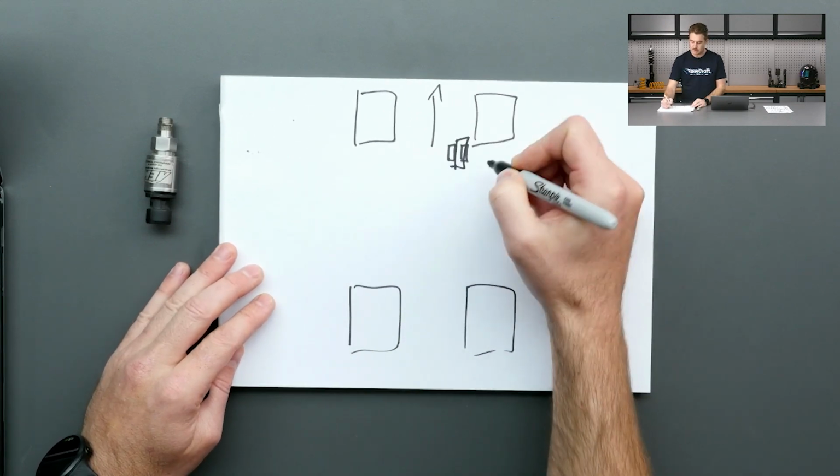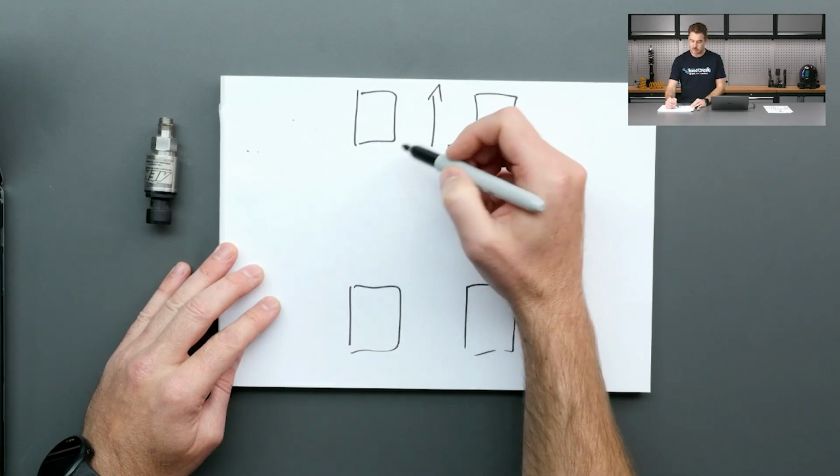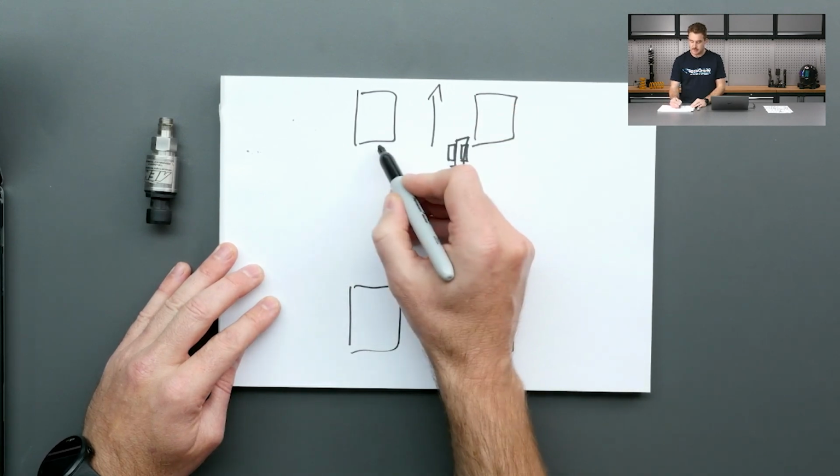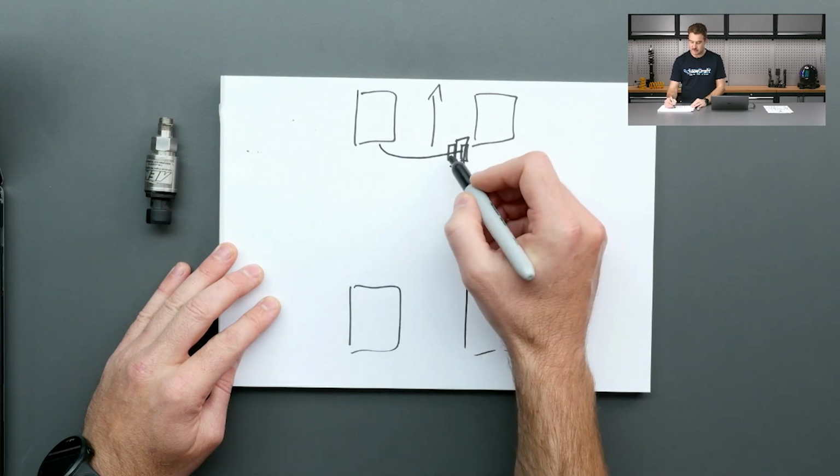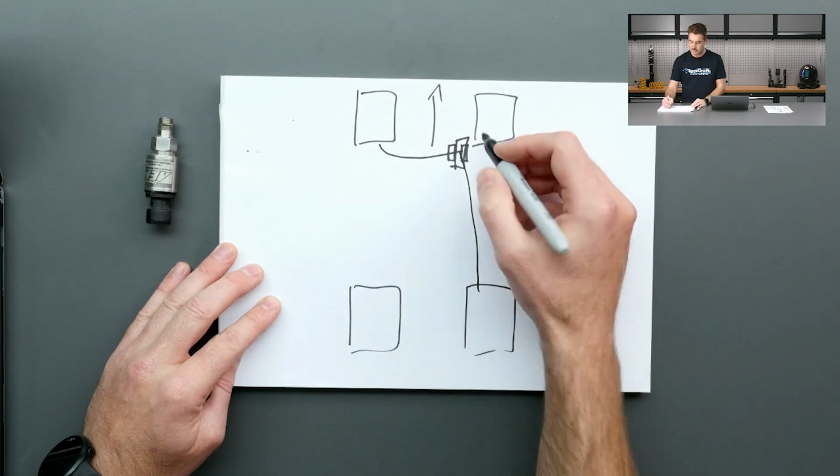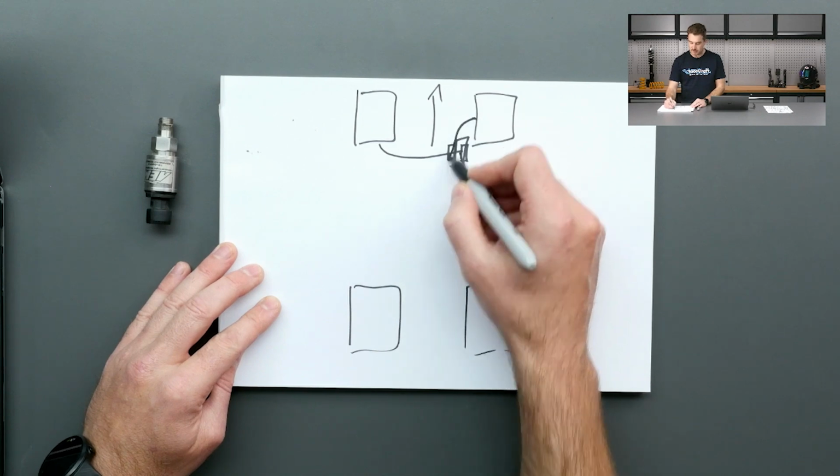single master cylinder, some cars will be plumbed diagonally. What I mean by that is one circuit will be the front left and the rear right, and another circuit will be the right front and the rear left.